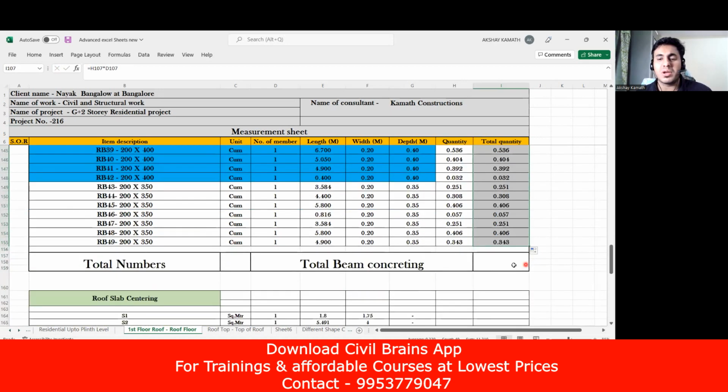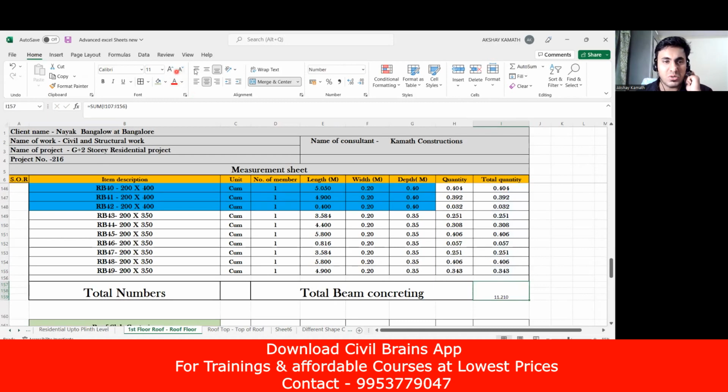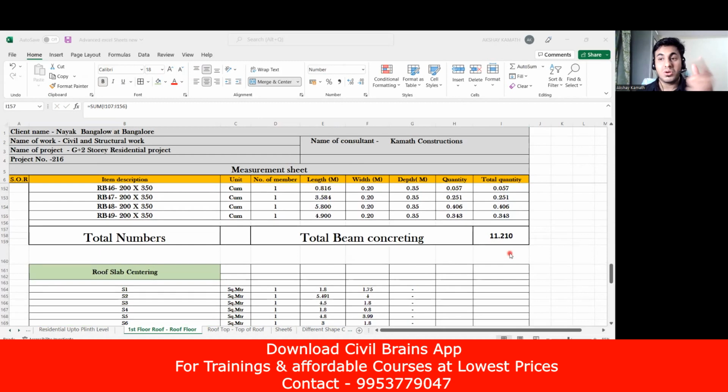Done. Now total beam concreting will be how much? You don't have to put the equal to sign. Keep your mouse here. Click on this thing. What is that? The auto sum option. Go to this auto sum and just press the enter button. Done. 11.210. So take it to the center, make it bold, increase the size. Enough. So the total concrete quantity required in my roof beam is 11.210 cubic meter.